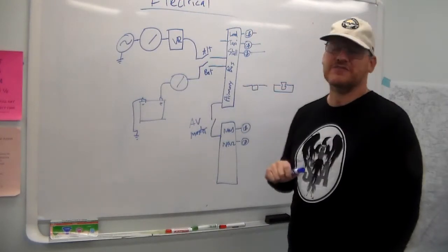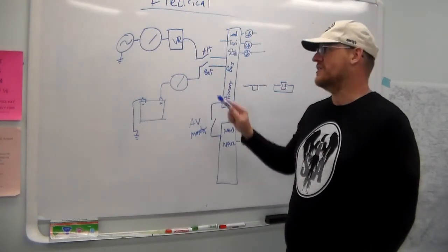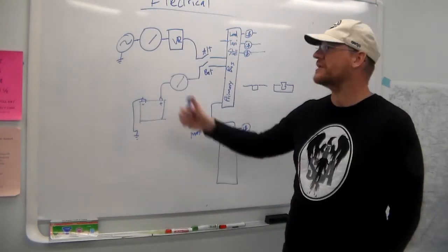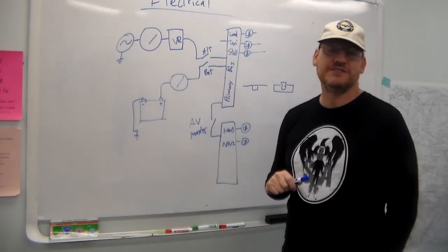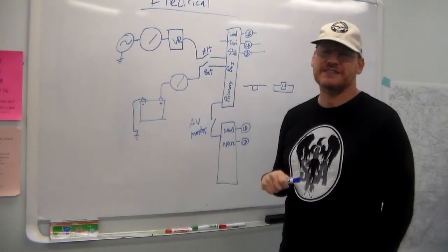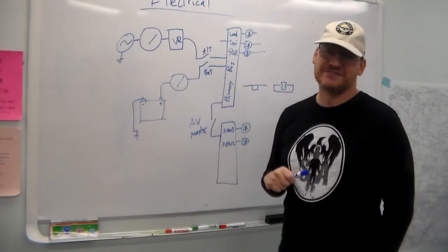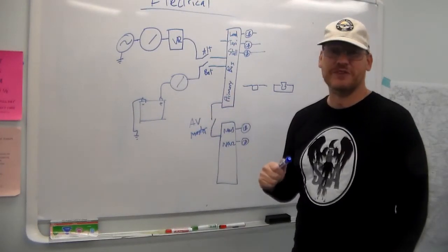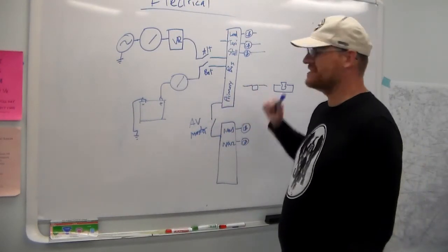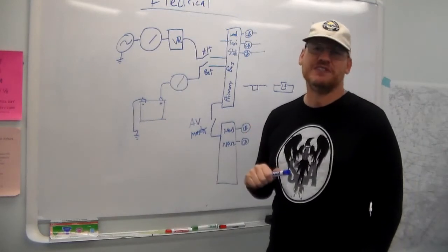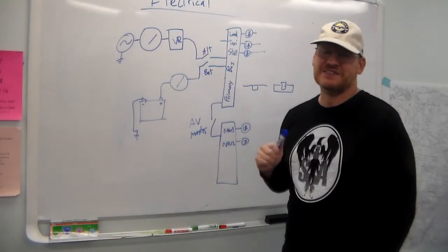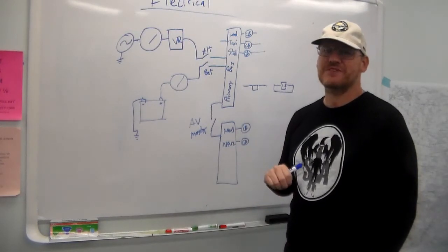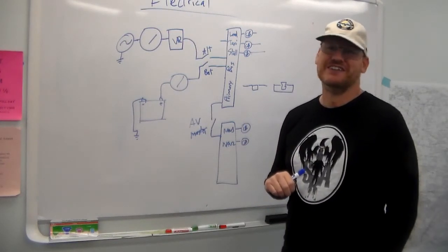So, that's kind of a rule there. So yeah, I've had it happen more than once where this guy is tripped. You just reset it and it's happy again. But yeah, don't be the guy that says, oh, it keeps popping, let me just keep pushing it in. If it's something you don't need especially, just figure it out on the ground. Don't figure it out in the air.